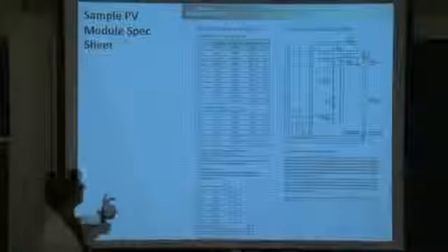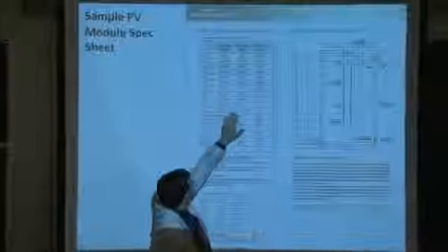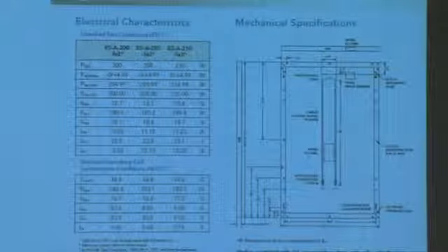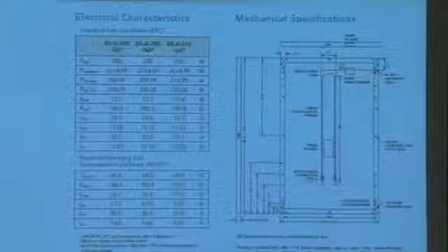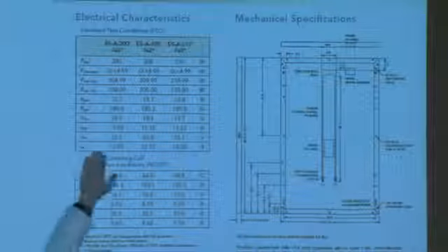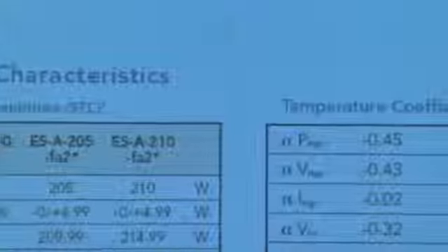Let's spend a minute here looking a little more deeply. These Evergreen Solar modules are the same size, but they have three different power outputs. And I think we went through this already, right? We have good cells, medium cells, and bad cells. And they're binned together in the different modules so that they can extract the maximum price from the consumer. So that's why you have three different power ratings for three different types of modules with essentially the same form factor, the same size and weight. They're just different quality cells. Yep, so that's that. Temperature coefficients, so forth.